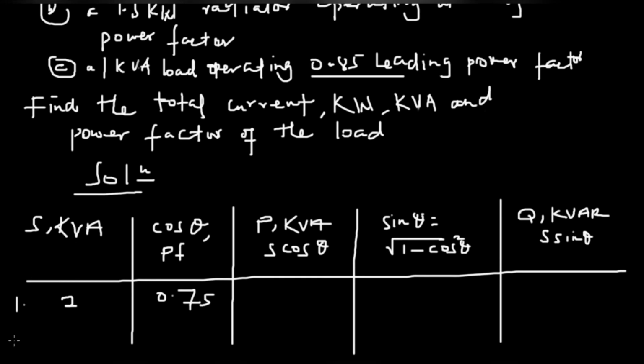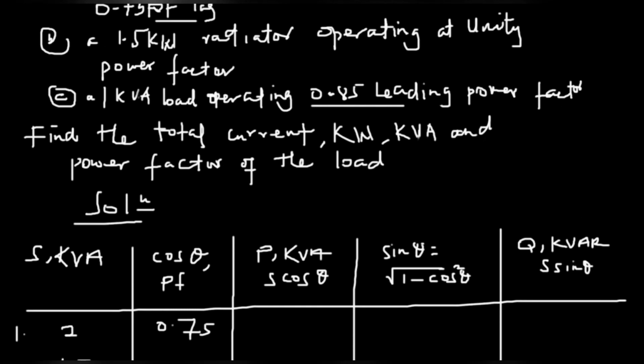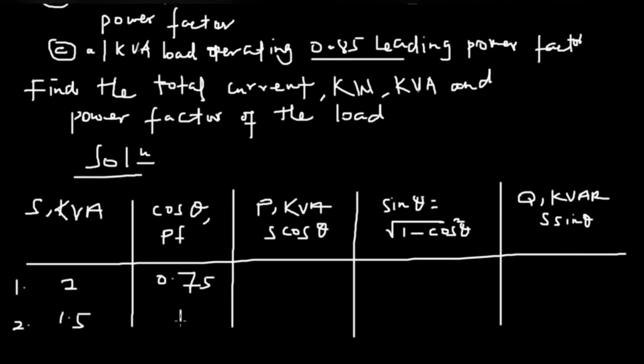The second one is 1.5 with unity power factor, so the power factor is 1. The third is 1 kVA with 0.85 leading power factor. Bear in mind that since it's leading, it's negative.